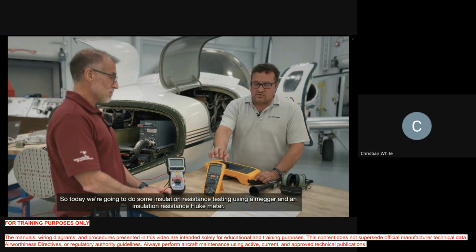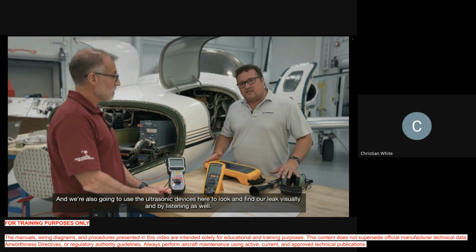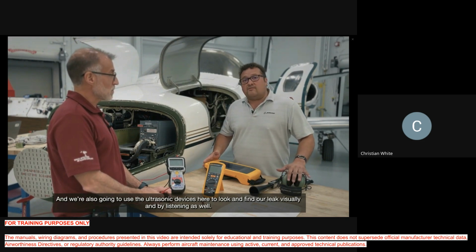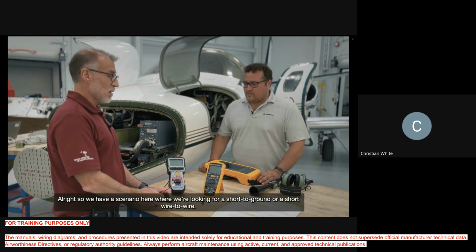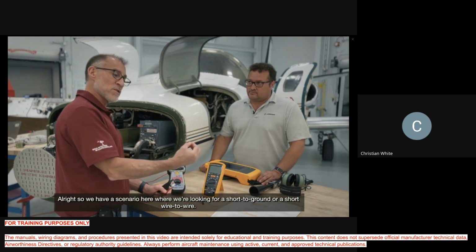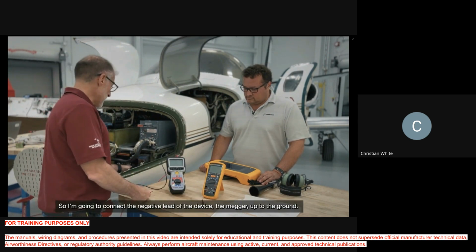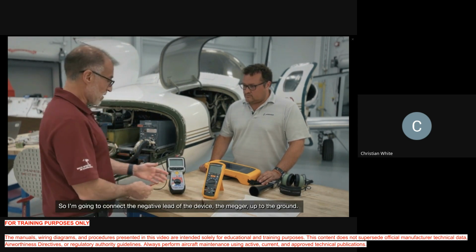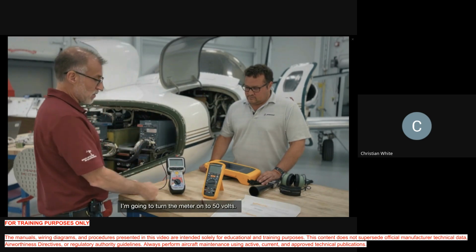And an insulation resistance Fluke meter. And we're also going to use the ultrasonic devices here to look and find our leak by visual and by listening as well. Right, so we have a scenario here where we're looking for a short to ground or short wire to wire. So I'm going to connect the negative lead of the device, the Megger, up to the ground. I'm going to turn the meter on to 50 volts.